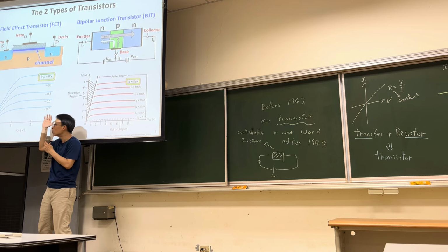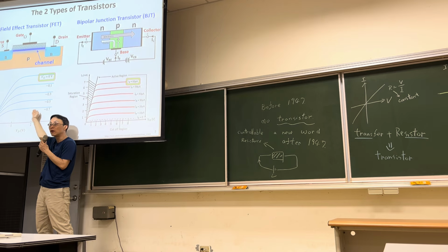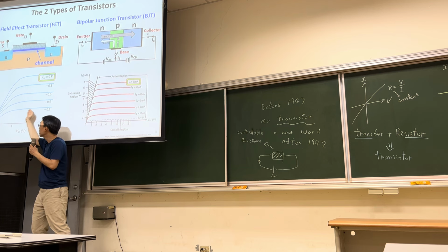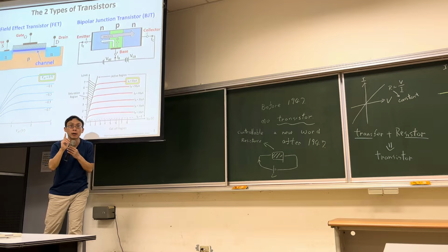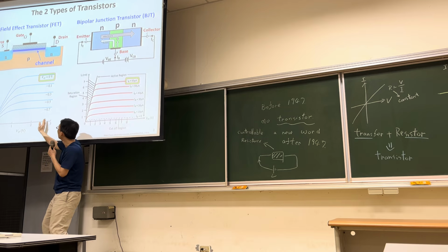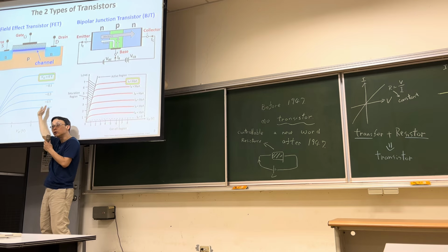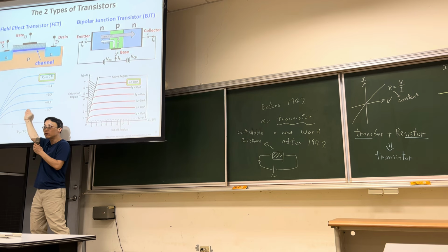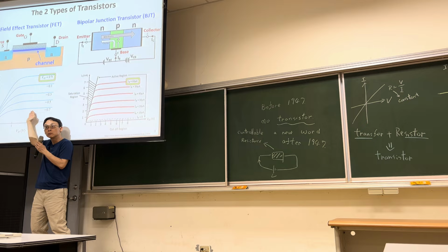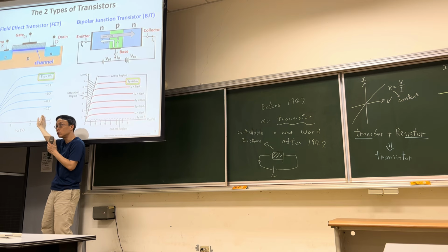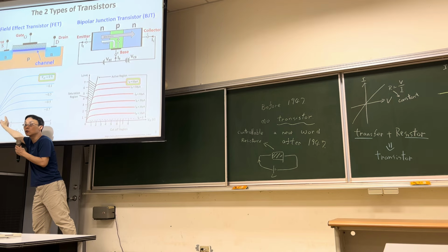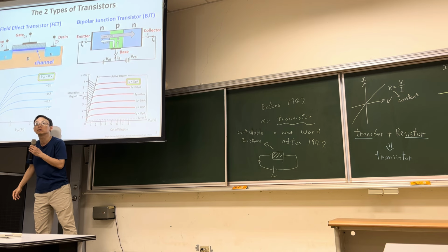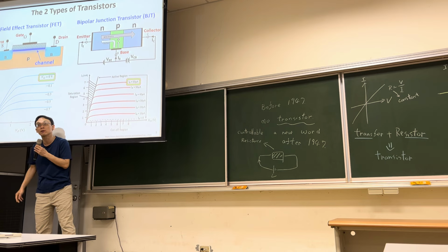So you have two regions. One is the linear region. The other is called the saturation region, where you have flat electron currents. In the operation of a transistor, it works in the saturation region because this region gives you stable currents for a wide range of voltage change. You don't work the device in the other region because it does not give stable current.